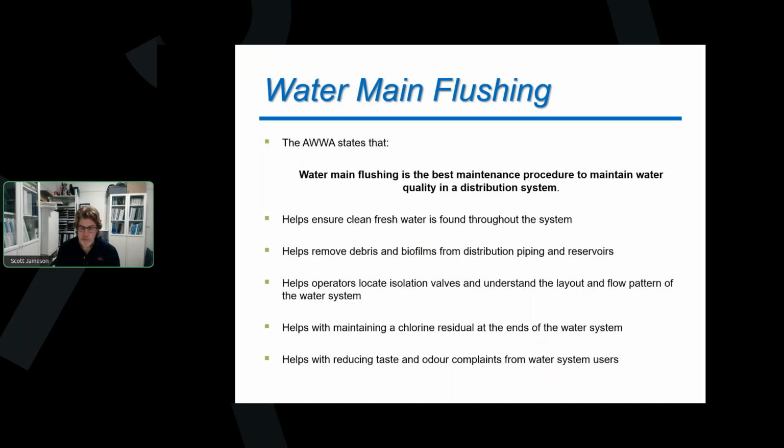Now, also with doing a unidirectional flushing program, it really also helps our operators find valves in their system and have a better understanding on how the water flows around their system. And hopefully we also get those other benefits like maintaining those chlorine residuals throughout our system. And hopefully we also reduce the amount of times anyone in our water system is calling in with a taste and odor complaint.